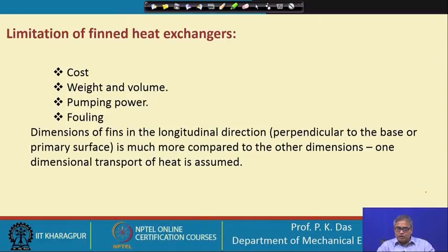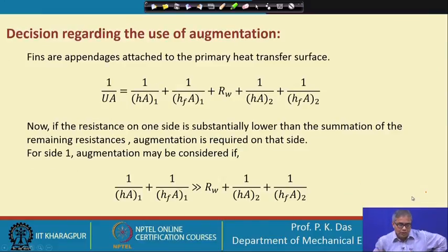The dimension of the fin in the longitudinal direction, that is in a direction normal to the primary surface or base surface, is much more compared to the other dimension. So, in many cases in the analysis of fins we can take the assumption of one dimensional heat conduction. This is very important, that in many cases our fin analysis is done based on the assumption of one dimensional heat conduction. So, with this background, let us proceed further.